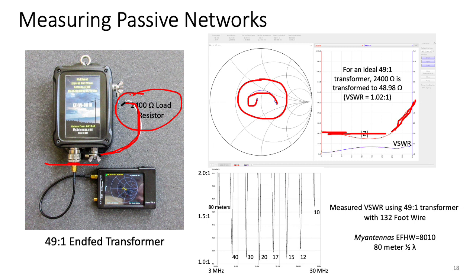Also, the one thing I should point out is that I cannot test using the NanoVNA such things as the transformer's ability to handle high power, whether it saturates or not. The power levels coming out of the NanoVNA are quite small. But in general, what I see here is that sure enough, my 49:1 transformation is doing quite well. I'm getting an SWR which is better than 2:1, and it seems to be flat over the entire frequency range from 3 to 30 megahertz.